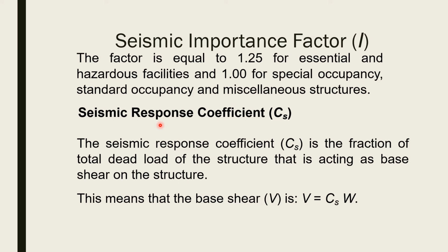It takes the total load of the structure and multiplies it by, for example, 20% or 10%, and applies that value as a horizontal load. That is called base shear. Let me read that definition: the seismic response coefficient is the fraction of the total dead load of the structure that is acting as a base shear on the structure.